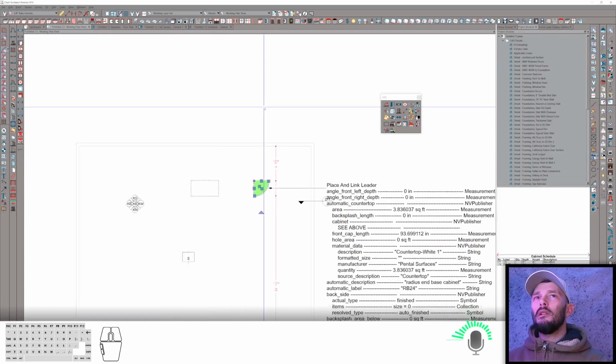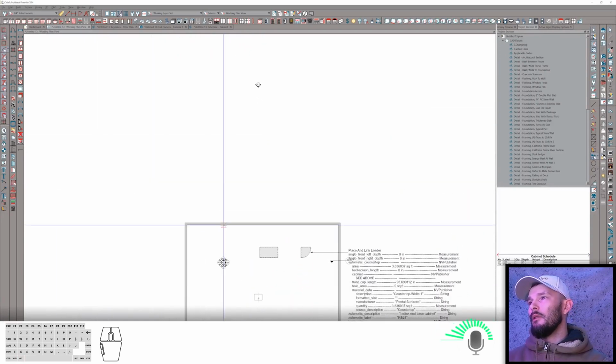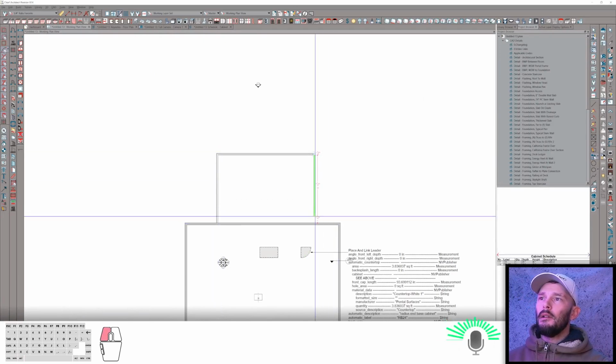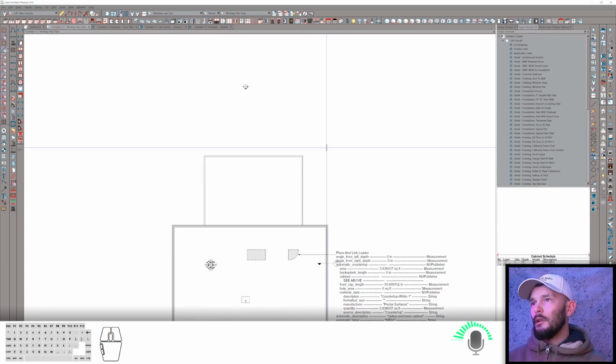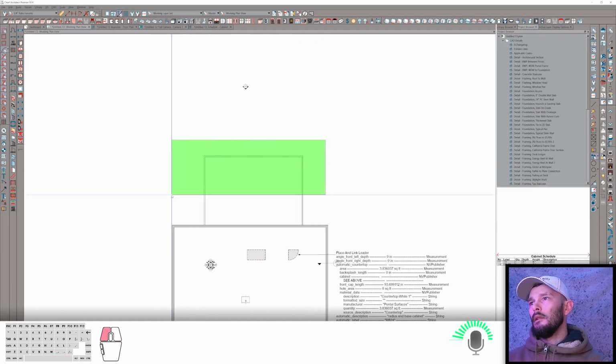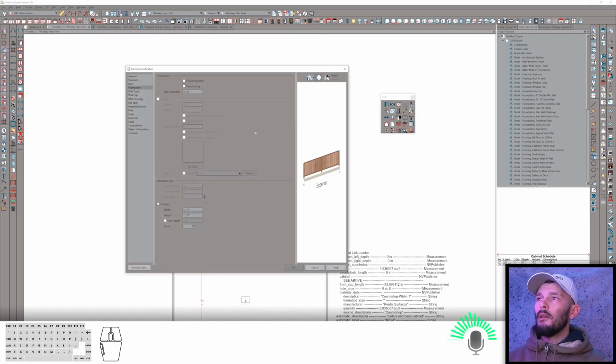I'm imagining that someone is using a railing as a post to rail setup to define a floor space, right? But this brings us back to another one of those posts where I'm going to change this to select intersected. Oops. Then I'll select these, open these up, and I might say that there's no room definition. It depends. I might need this to have room definition.